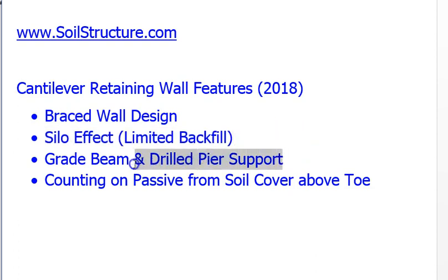The other feature we added is to have a grade beam and drilled pier support reactions. So we have a separate grade beam software and a separate drilled pier support. But if you click on this feature, you'll get the shear, torsion, and the axial load and the bending moments.